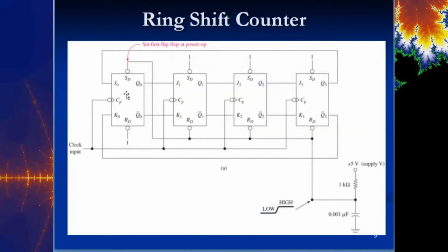So it's got that same 4-bit structure here, okay? Notice that in this case, it's the same structure where the Q feeds into the J here, except for the very first one and the very last one. And all you do is ring. I don't know if that's the official term, but I always say you ring this last one around to the J, right? The very first J. And so you see here on initial power up, using our automatic power up reset, right?